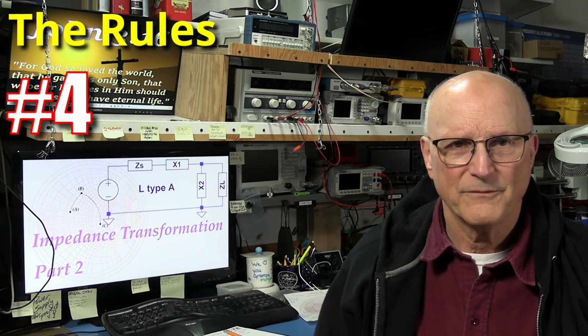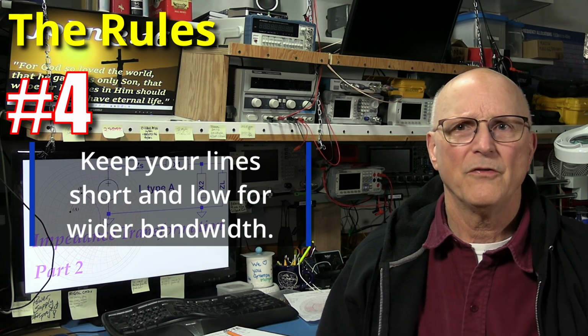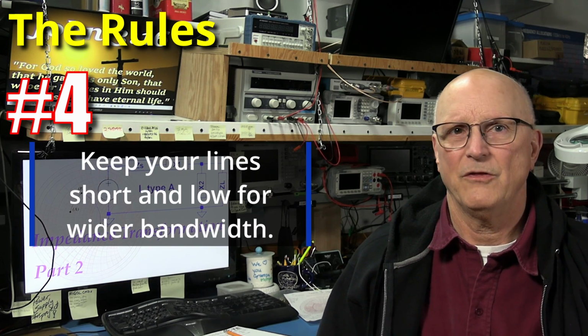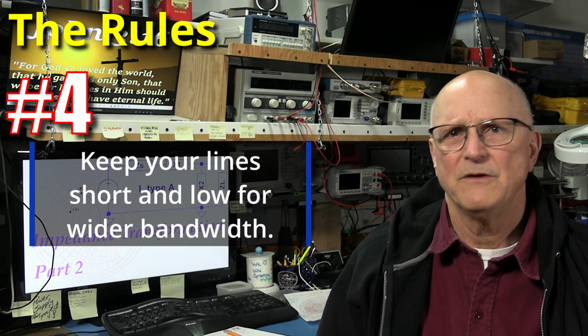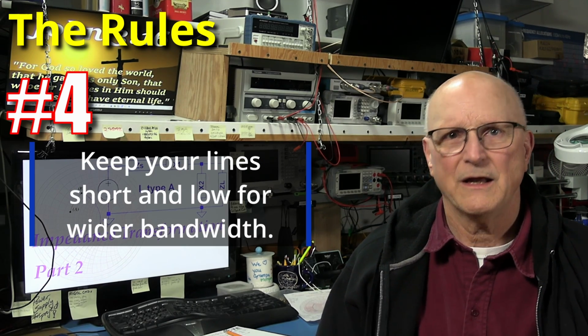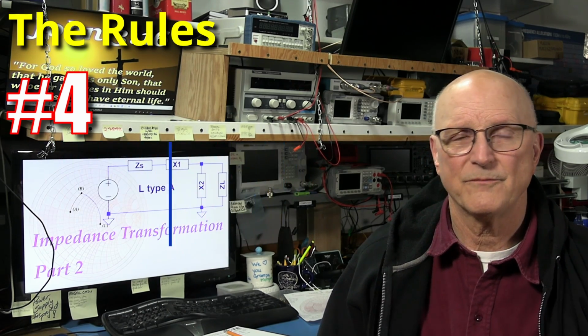Rule number 4. The longer the lines between the two impedances, the higher the Q and the narrower the bandwidth. The further away from the equator, the higher the Q and the narrower the bandwidth. Keep them short and keep them low for wider bandwidth.